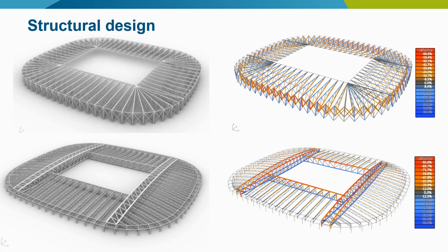Because we used Karamba, and with Karamba, you can do FEM analysis, but you can also do a cross-section optimization. So based on the model, you can ask to Karamba, what is the optimum cross-section and what is then the total weight of my structure? And this gives an indication of the cost for the structure. So in this way, we could compare both options and also advise others in what to do and what influence design decision has on the total cost.